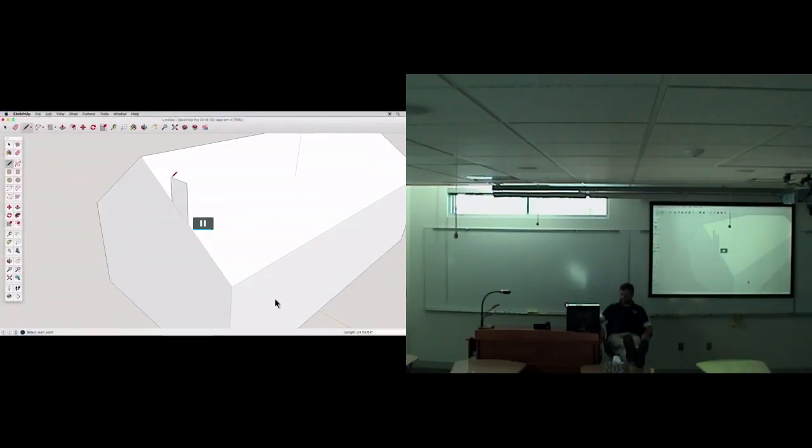With the surface drawn, use push-pull to extend the chimney across the roof to a point you are happy with. Use push-pull again to complete the chimney. By pulling across the roof surface, extra edges have been created, but these are easily erased. Any lines drawn across coplanar surfaces can be erased to form one larger surface. We call this healing the surface. Use the eraser and erase these two extra edges.